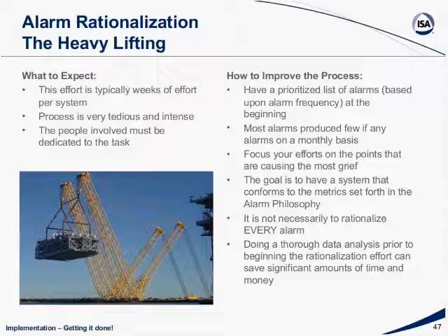Now, having said that, you may get something that only alarms once a year, but when it alarms that once a year, it shuts the facility down. Yeah, you're going to want to rationalize that to see what you can do to eliminate that. But for the most part, you really want to stay with a prioritized list and taking a look at things.